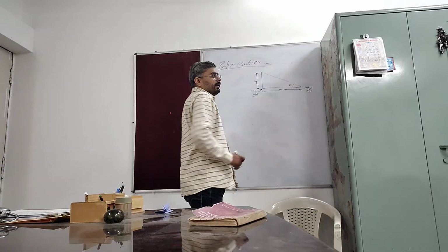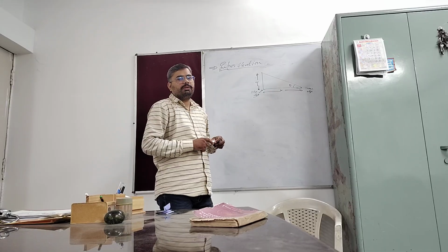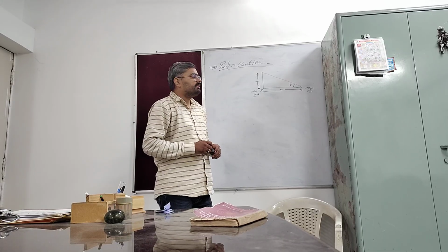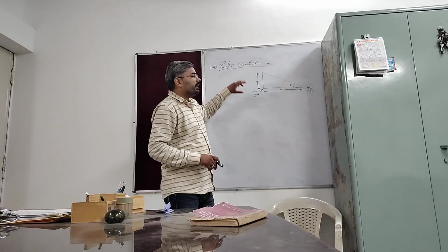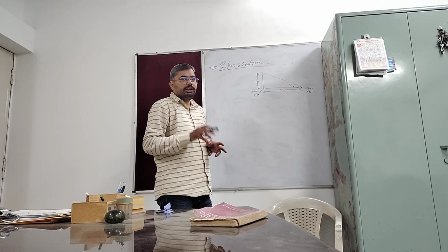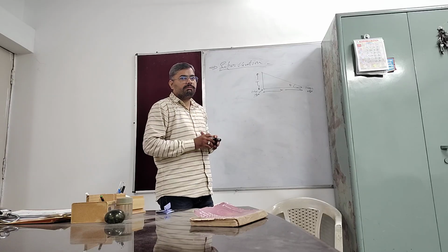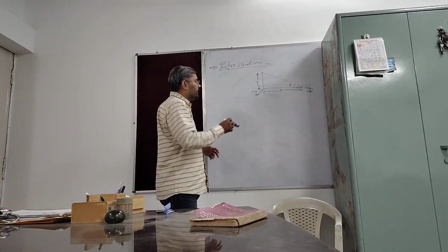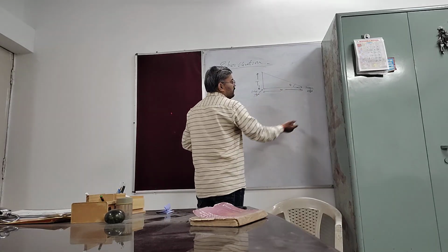So students, what is super elevation? Today we have to introduce super elevation from the transportation engineering subject in the civil engineering department. We have to consider super elevation on highways, roads, and in railways. Railway super elevation is calculated differently than highway. At first we have to select the width of the pavement, that is W.